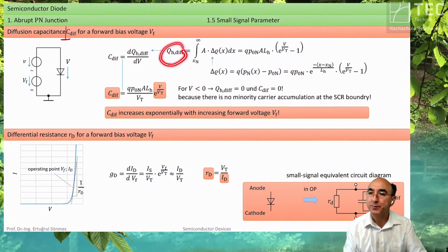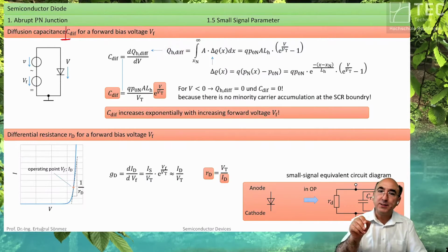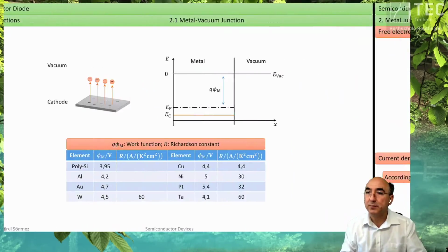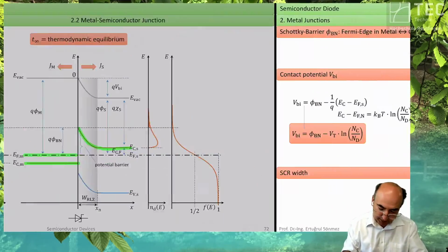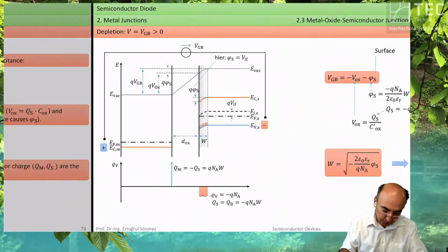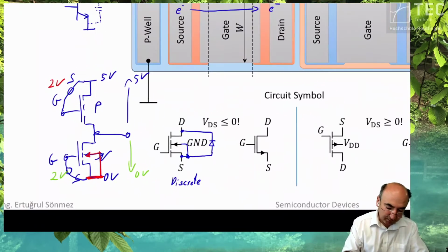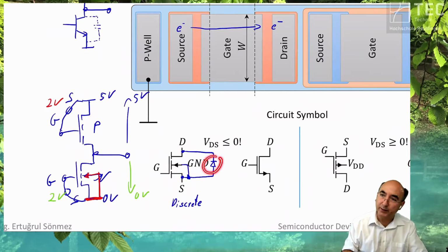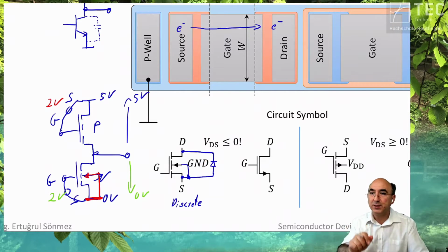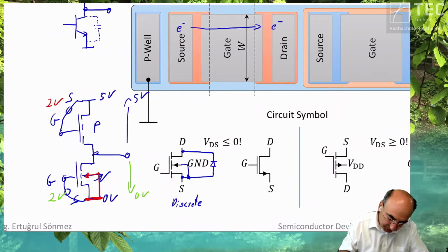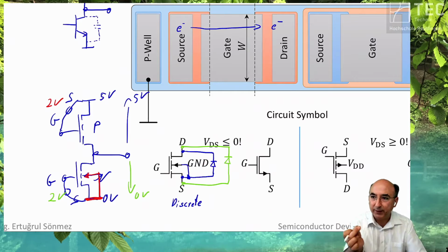diffusion charge. So this diffusion charge is placed into the substrate of the MOS, and this charge kills the function of the MOSFET. And therefore, you have to prevent this condition. And usually, you do this in circuits by, so if you want to prevent this diode to be forward biased, what you do in silicon, you put an additional physical real diode in parallel, real as a device, but a Schottky one.